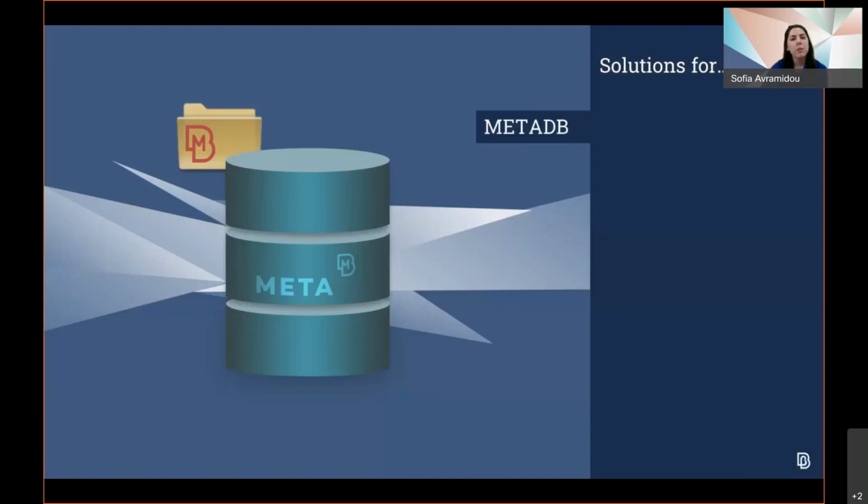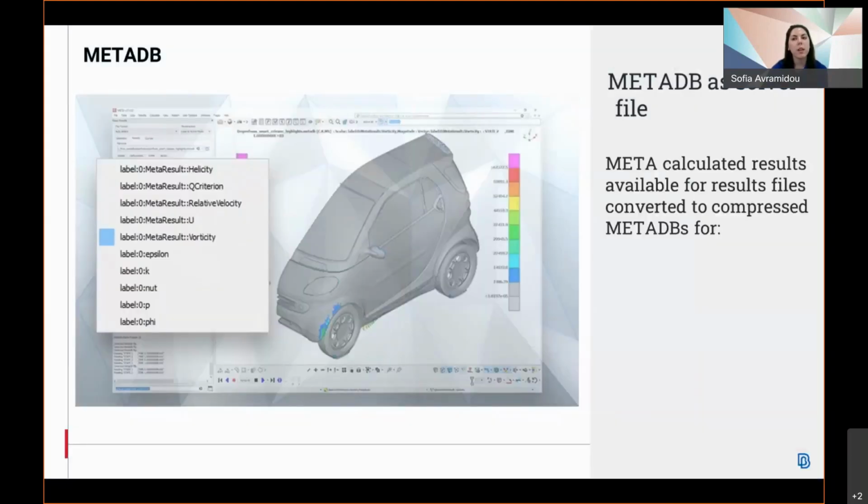Keeping up with the advancements in the MetaDB file format, the functionality to use the MetaDB as a solver file and therefore calculate derivative results is now available for more solvers, namely ANSYS, PERMAS, OpenFOAM, and StarCCM+. It's reminded that in previous versions this was already made available for LSDyna, Nastran, and Abaqus.